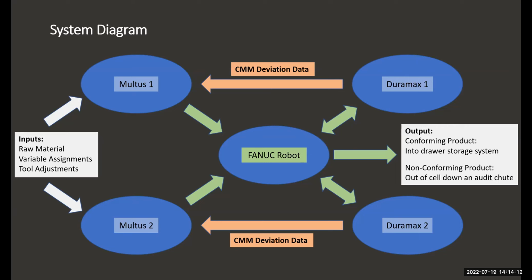Initial logic for this algorithm was set with an offset adjustment being applied at about 1/4 of the CMM deviation value to slowly walk a feature into its nominal dimension. Monitoring of the dimensional stability of the parts during manufacturing showed that some adjustments needed to be more aggressive, while others needed to be less aggressive to achieve this stability.